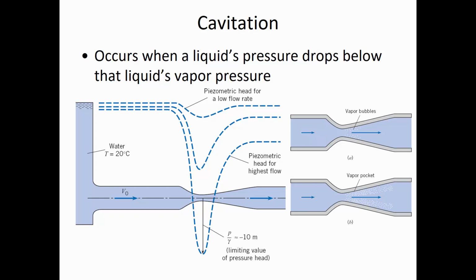But it doesn't necessarily have to be at high speeds that there's cavitation. The cavitation can form either because of a velocity change or because of a big absolute difference in velocity, like on the front side of the propeller versus the back side of the propeller. There would be a pressure difference between the two. So I don't know if that addresses your question.